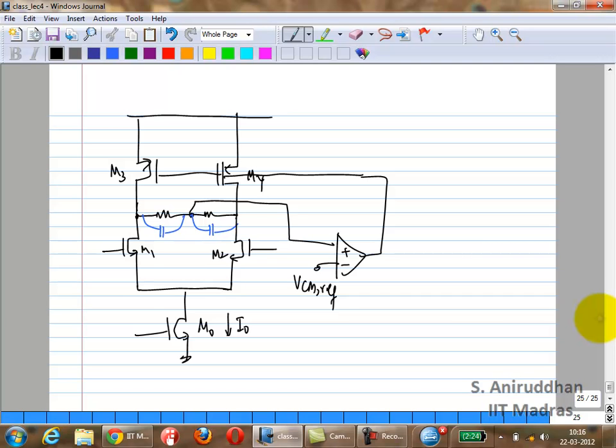You know several kinds of amplifiers. We have studied a lot of amplifiers. A common source. Okay, but I thought in yesterday's class we discussed that common source is not great. Common drain. If you don't want amplification, you can use common drain. We'll come back to it, but for the source follower we know that there is a DC shift, so it may not be ideal, but it can be worked into your amplifier. What else apart from that?